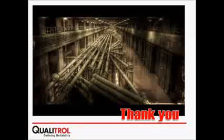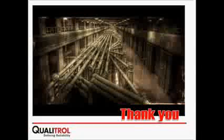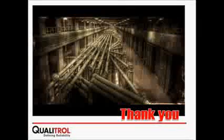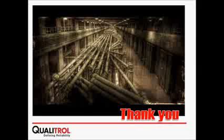And there are lots of examples. I don't know how many we have captured in terms of formal paper or white note, but we'd be happy to discuss it one-to-one and share our findings with you, what we can do to justify the value of online continuous monitoring, which you can achieve with a portable unit, especially for a transformer. One portable unit can do continuous online monitoring for a transformer. For a GIS, it may not be enough. In that case, we do offer continuous online monitoring for the GIS, which could accommodate hundreds and hundreds of sensors if need be. And there is a proven business case on the cost benefit for that.